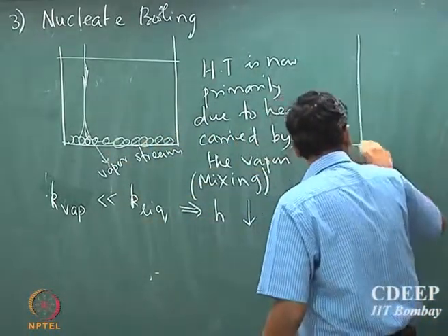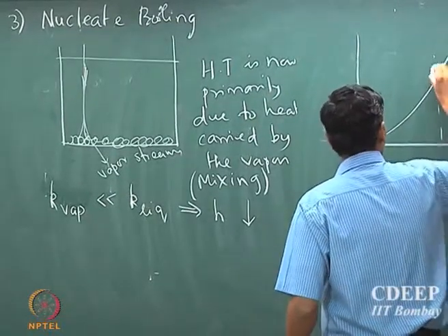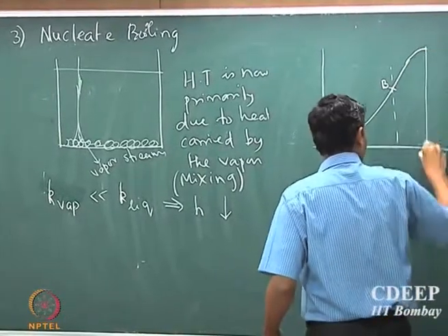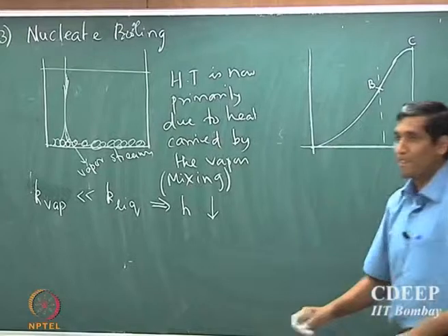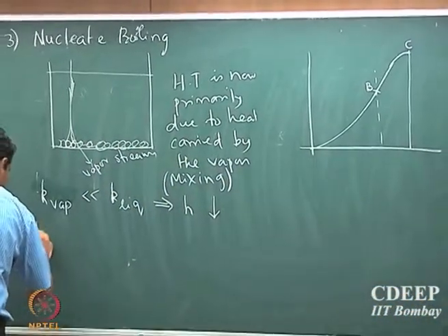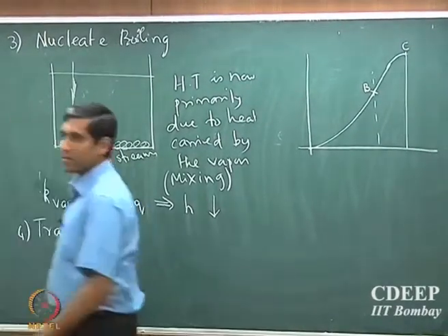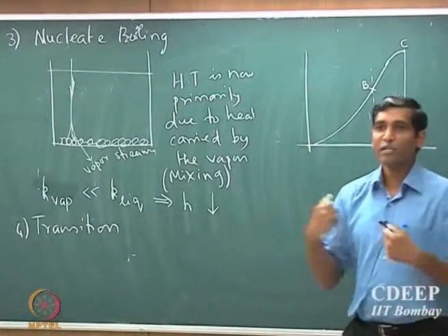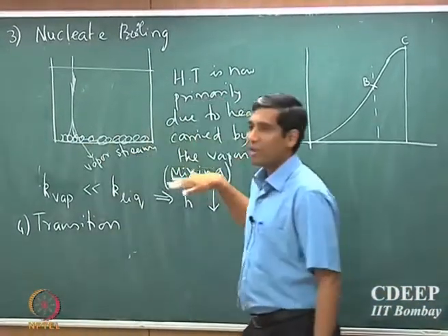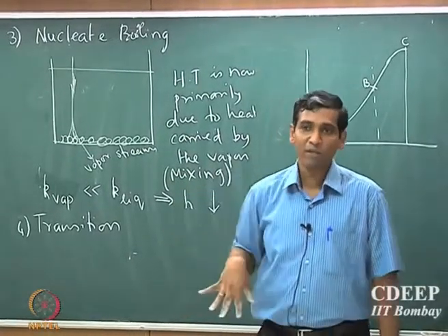And the boiling curve here is, so if I put, so that stage is all the way up to the maximum, okay. And what happens after that is called the transition stage, okay, where you cannot distinguish whether the bottom surface is now in contact only with the fluid or only with the vapor phase.